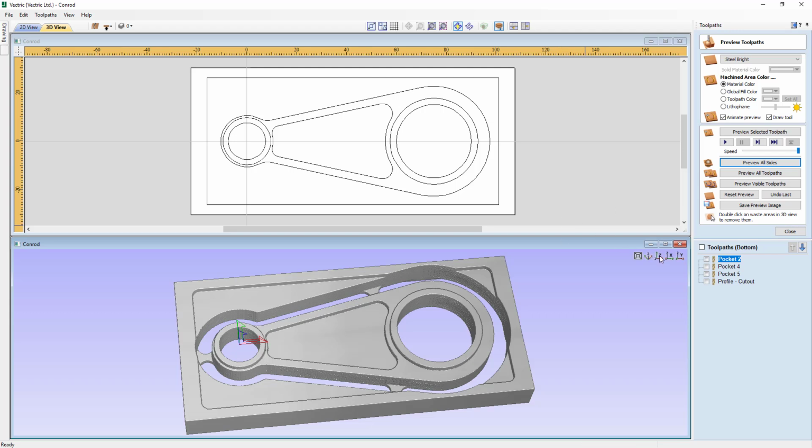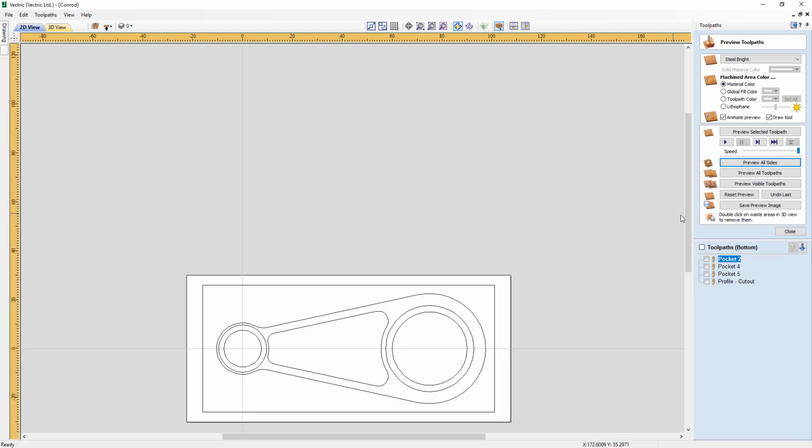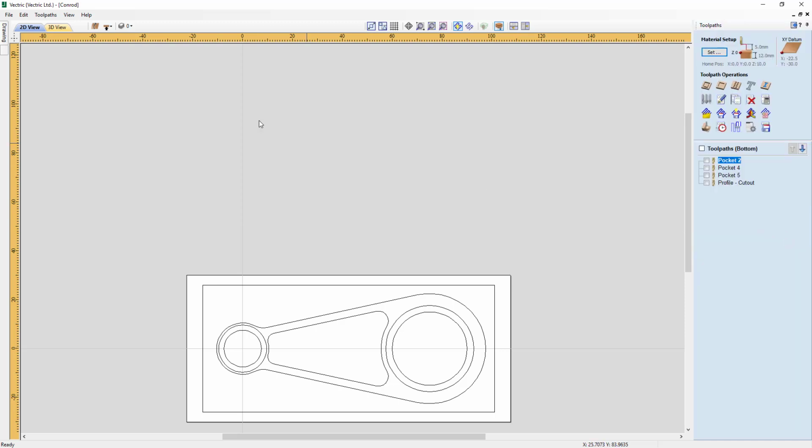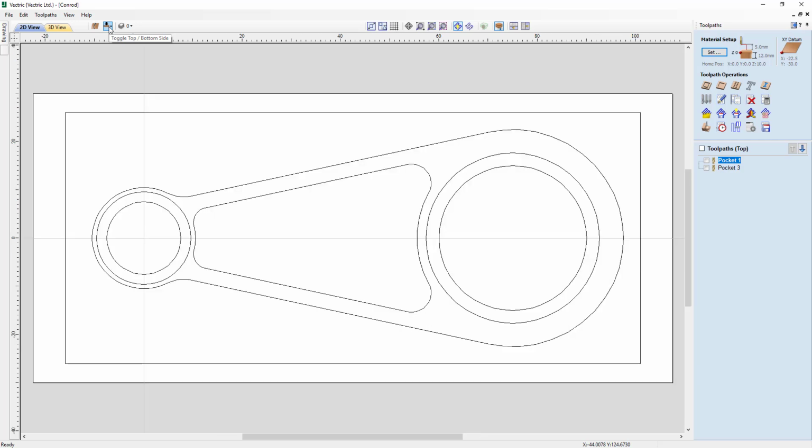So we're going to look straight down on our 3D view again. We're going to maximize our 2D view, and then we're going to close our 3D previews, flip to our front, and then we're going to press F on the keyboard. That way we'll actually zoom into the full width of our 2D view. Now we use this vector to define how far we want it to go out, or the part of our material that we wanted to actually machine out. This was the boundary of it, the maximum boundary.